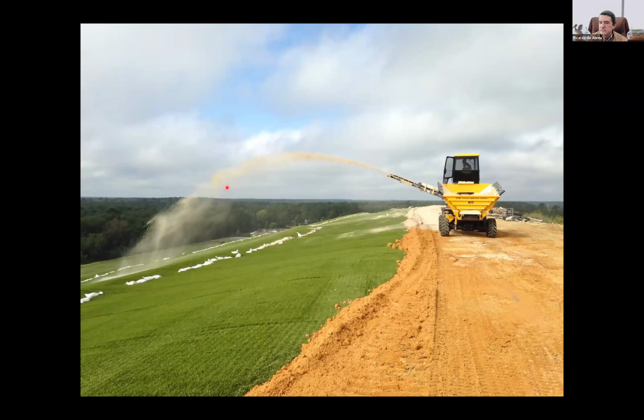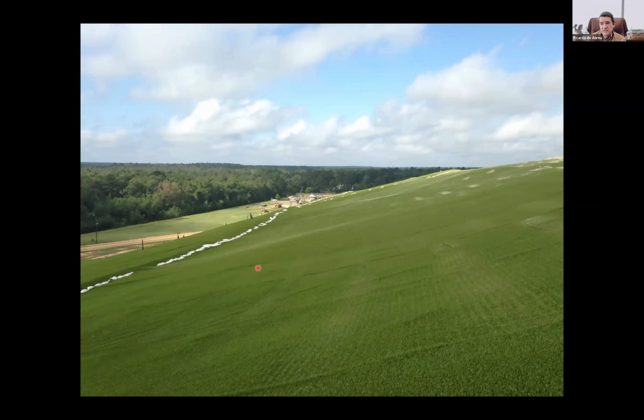So this was the way they deployed the sand, and they would come and literally brush it into place. And believe it or not, we would make sure that you have, I can't remember if it was half an inch, I think half to 0.75 inches. And we measured in several locations if the infill was in place as it should.